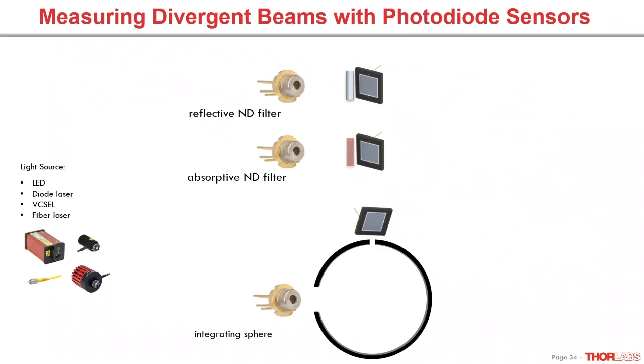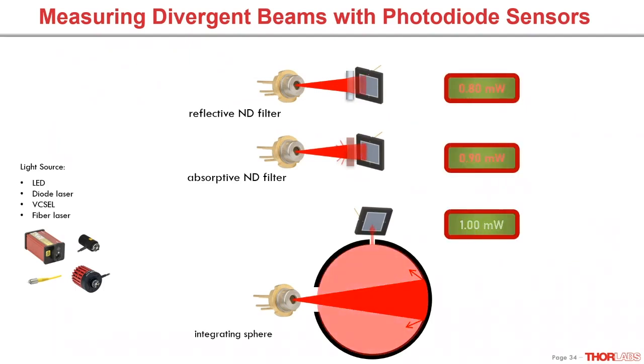The next observation we want to make is the behavior of sensors with divergent beams. Divergent rays are emitted by diode lasers, LEDs, or fiber tips. So with photodiode sensors, care must be taken to not overfill the active surface of the photodiode. Here you also have to be aware that the sensitive area of the photodiode sits a bit recessed behind the filter. So even if your beam fits inside the aperture or inside the filter, it can diverge so that the photodiode gets overfilled.